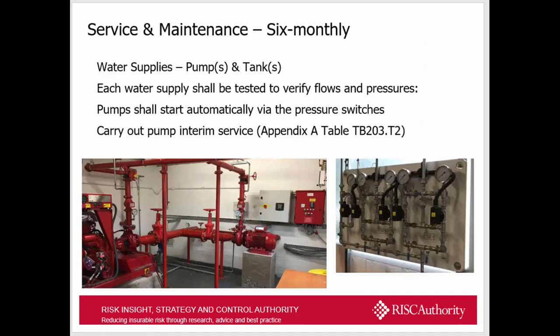Water supplies. Still on pumps and tanks, again, we've just mentioned the water supply should be tested to verify the pump shall start automatically via the pressure switches. And there's also a requirement in TB203, there's an appendix which we come on to in a few slides' time, that shows you all the requirements that have been put together by the manufacturers, and you carry out a 6 monthly interim service on the pumps.